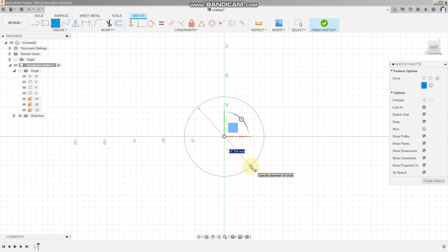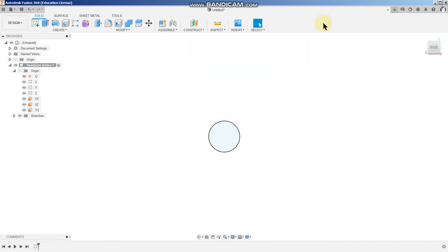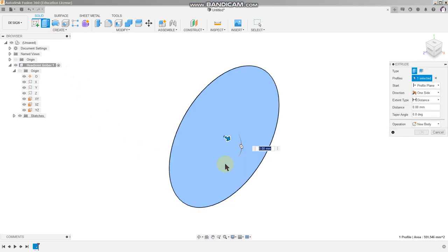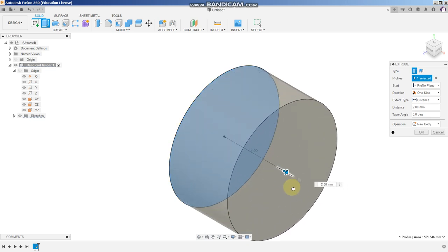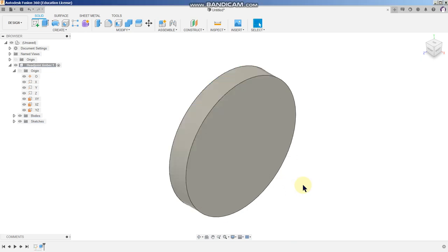And we're going to create a circle with a diameter of 26.5 millimeters. And we finish the sketch. Now the circle is looking straight at you, so what I always do is go up here to the location dice and click on the home. Now I'm going to extrude that. Extrude simply turns the flat disc into a cylinder. I'm going to make that 4 millimeters. Done.